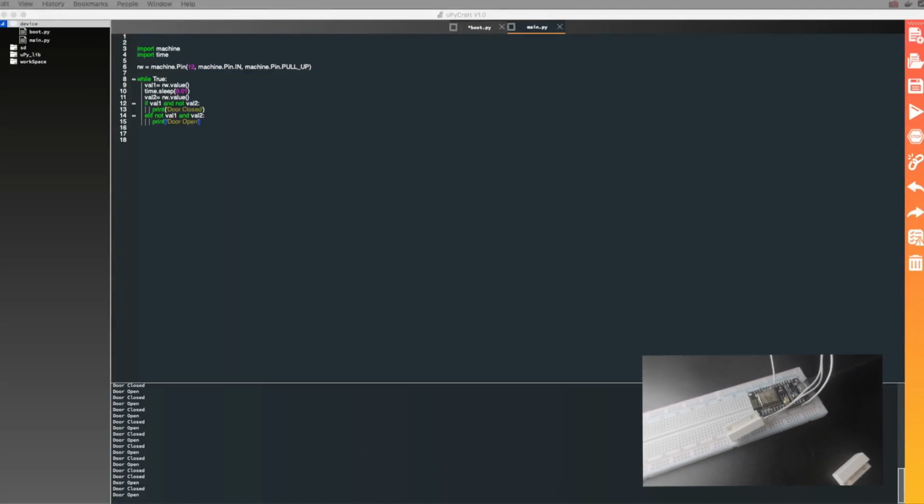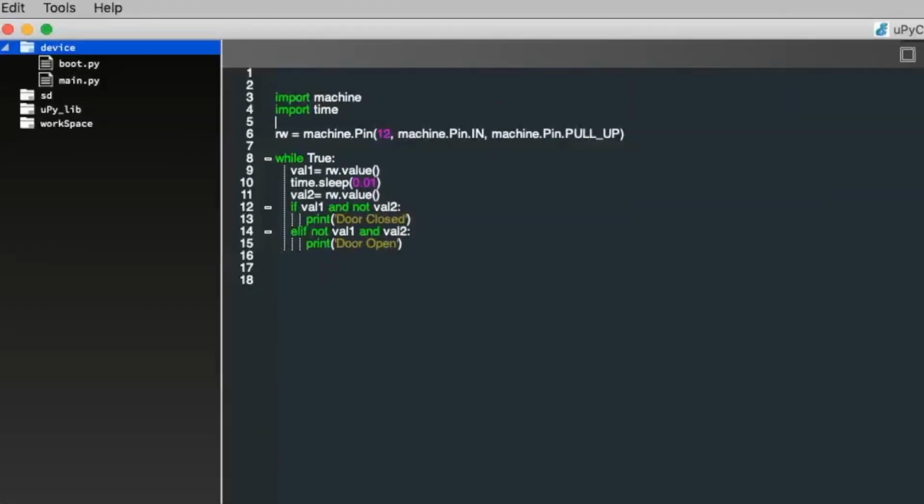So if I were to take this back, and walk through the code with you here. I should also say MicroPython is actually a modified version of Python. So it's a very lightweight version. I wouldn't say that it has all the capabilities of regular Python. The other thing to keep in mind is these microcontrollers have like a megabyte of flash memory. So there's not a lot of memory in this, so it's really meant to do lightweight tasks. But basically, machine is a Python library that helps to map to your different GPIO pins on your actual microcontroller.